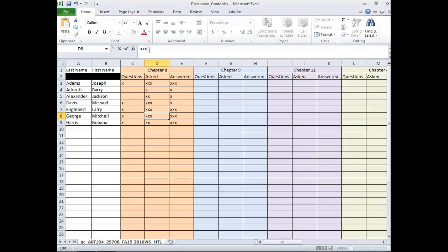I know we can use pressure sensors to measure flow, but we have to send it through some type of obstruction. So you have a high pressure side and a low pressure side. The temperature, I don't know. Tell us the answer to that. It takes two of them. I figured two because that's how many pressure sensors it takes.